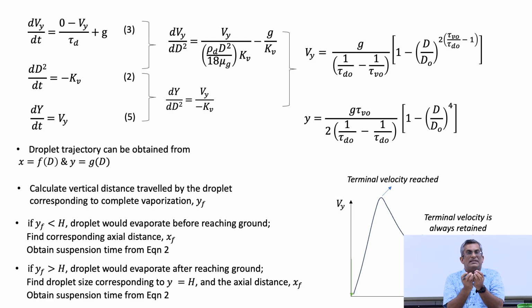So you need to consider the characteristic time scale of each process and make sure that the delta t or the step size is smaller than all three of them. But usually the momentum response time is smaller than the vaporization time. However, it depends on the application. You should not always assume, rather make an estimate and then decide delta t.